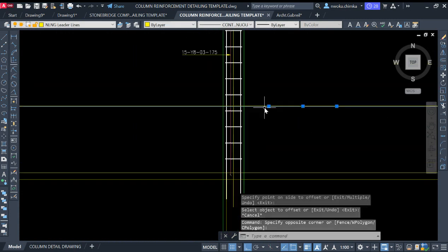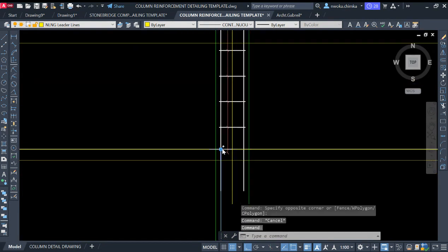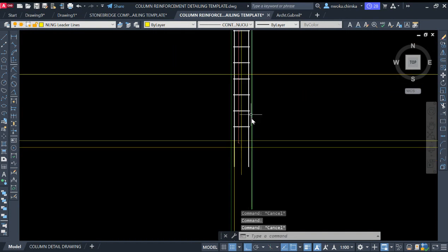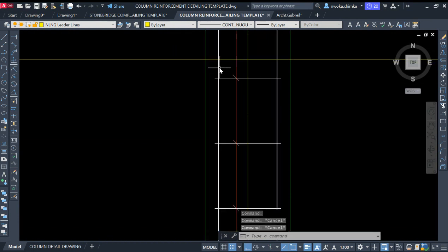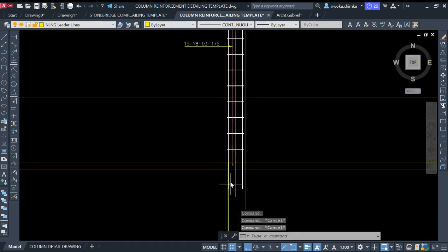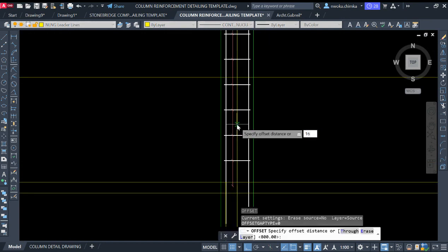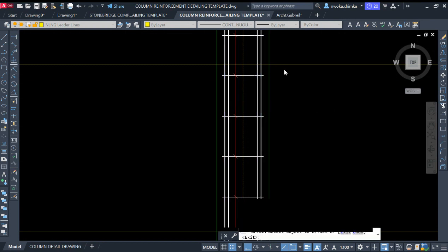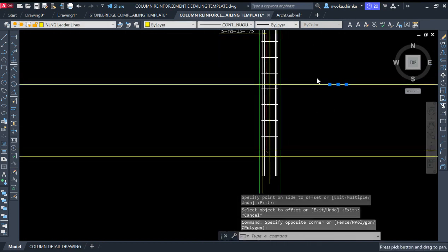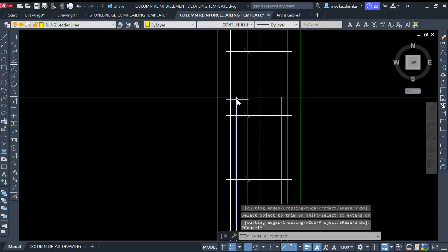With this point, this is now where my reinforcement will start from. I can leave this here first. Now, I'll offset my lap distance for the reinforcement of the column to the foundation, which is the connection. I'll offset 16 outward here, 16 again outward here. I'll click on my lap length here and trim off this offsetted one. This now forms our lap length.